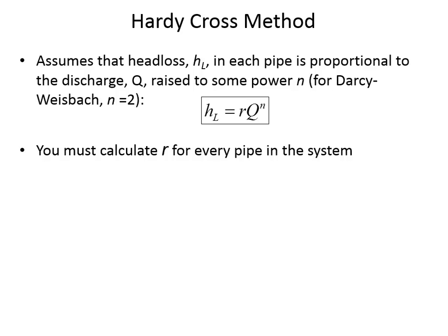Okay, so as I was mentioning, we're going to have to estimate initially both an F value and a Q value when we get started. And how can we start with an estimate of F? What's a good way for us to have something reasonable to begin with? Do we just pick a value in the middle of the Moody diagram? Look at pipe material first. Okay, pipe material will have something to do with it. The fully turbulent flow assumption will be a great way.